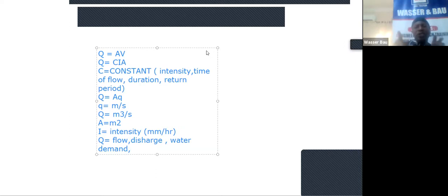So that's why you see some of these areas in Abuja that are being flooded, Lokogoma, Lugbe. The reason is that people are building houses more and more. So we are getting more paved area. People are using interlock, people are using macadam, many types of things, so we are not having that deep infiltration. So at the end of the day, you have massive surface runoff which is not designed for.